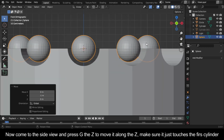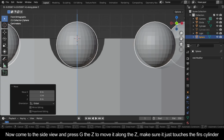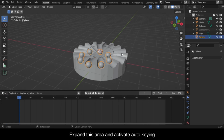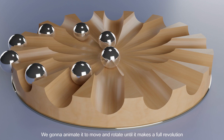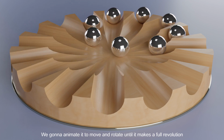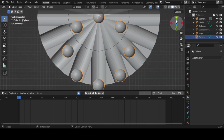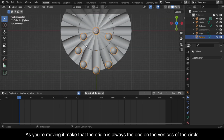Now come to the side view and press G then Z to move it along the Z. Make sure it just touches the first cylinder. Expand this area and activate auto keying. We're gonna animate it to move and rotate until it makes a full revolution. As you're moving it, make sure that the origin is always the one on the vertices of the circle.